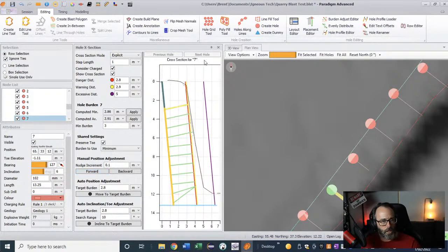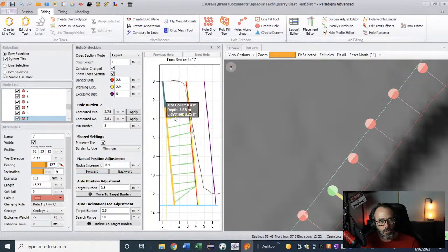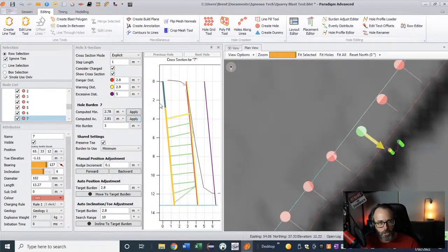Yeah. So now you can see this. Let's say you really wanted that to be the case forward, then you're in the warning state. So now you need to think about increasing your stemming on this particular hole. Perhaps you want to increase the stemming to 4 meters so that you don't blow out the crest, but you really want to place it in this position. So this is the important aspect of face design, is you need to consider your charging, where something is underburdened, overburdened.